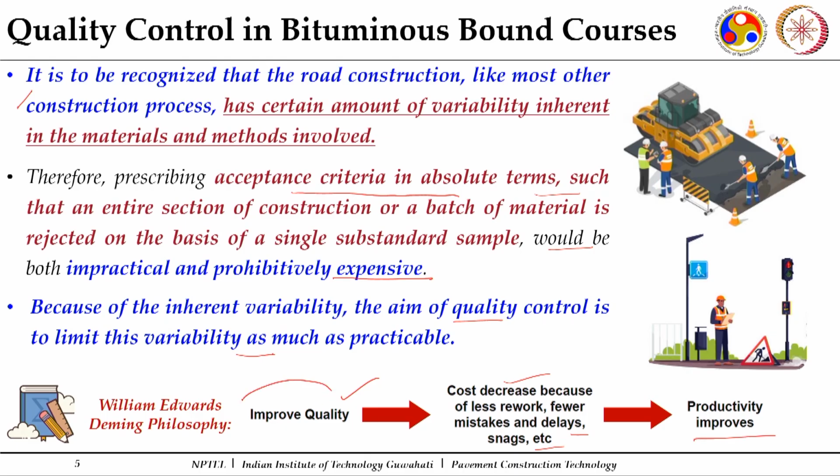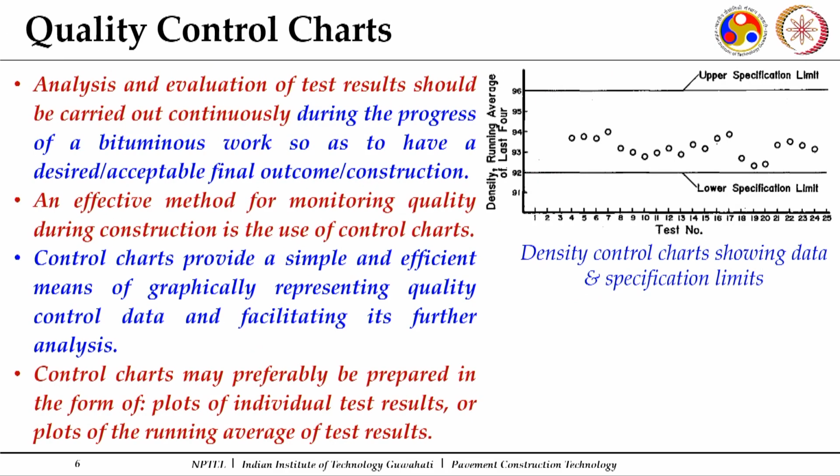So, quality checks are very important for any particular course, and when it comes to bituminous bound courses, since these are the courses which are going to take the maximum loads, and are the main structural components of your flexible pavements, the checks and the controls have to be much better for these courses.